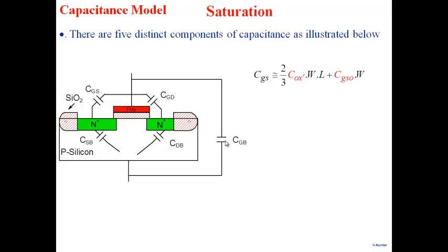Okay. And so I was telling you yesterday that the capacitance between gate and source has two components. One component comes about because of the charge in the channel. There's a charge in the channel, and as you change the gate voltage, the charge in the channel enters through the source or exits through the source, and it can do that through the drain as well.